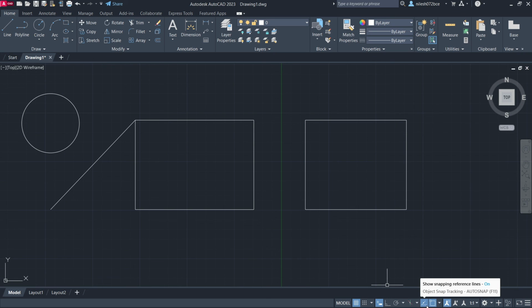So this will track all the reference lines, and this will snap cursor to 2D reference points. Both will work simultaneously. So in this way, we have seen all the options of this status bar. The first one was grid mode. The shortcut option is F7, then snap mode F9, and then this dynamic input mode, and here the ortho mode F8, and then the polar tracking F10.